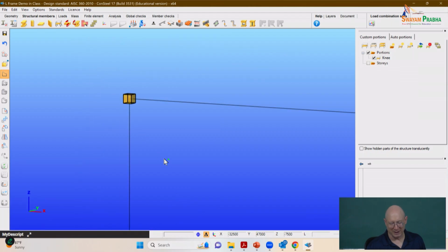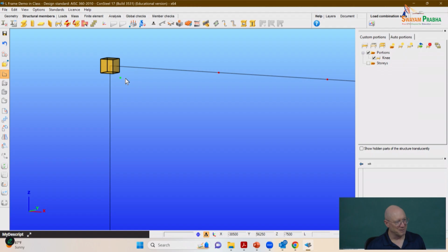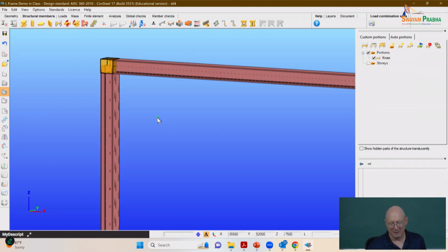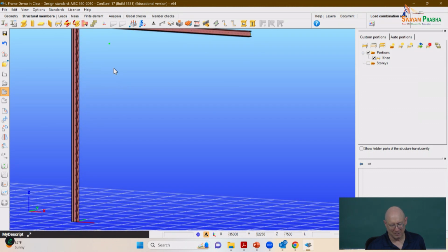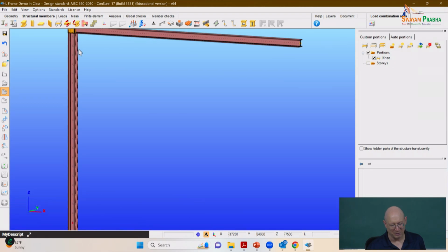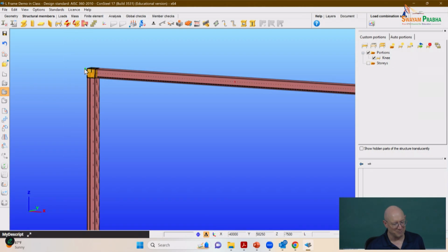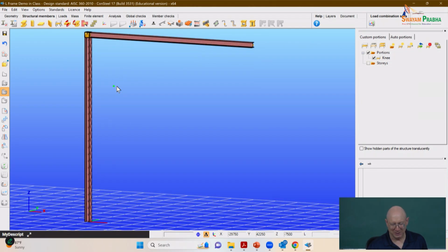Now you can see that I've got a little yellow box there at the corner. That's telling me I've properly implemented my model in Consteel that represents how the continuity, including the warping, works at that particular joint. If we come back to our hidden line view, you can see the columns, and then the yellow or orange area there is where we've got the panel zone. So we're almost ready to run our analysis of our frame now.